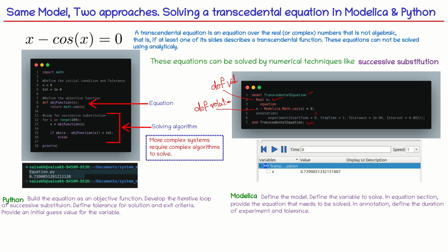So regardless of whether your model is steady state or just a mathematical model having nothing to do with time, you have to iterate it over a time period to simulate. By default, OpenModelica provides 0 to 1 second as a time interval, which can be modified anytime. Then the tolerance and the time interval, like how many iterations to run, are also handled accordingly.